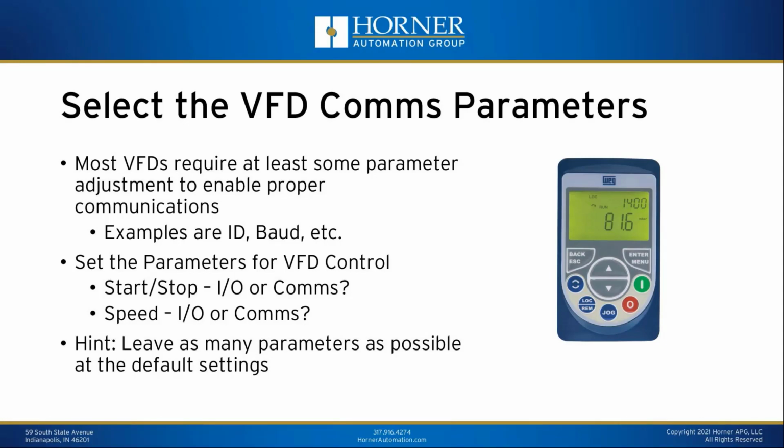In addition to that, there almost certainly will be parameters that you need to change that aren't directly related to communication necessarily, but are related to where the drive is looking for its start-stop signal. Is it looking to the terminal strip? Is it looking to its own keypad and potentiometer that may be wired to it? Is it looking to the network for those functions? Almost all drives have parameters that allow you to select where those start-stop signals and speed control signals are coming from. So those will need to be adjusted through drive parameters as well.